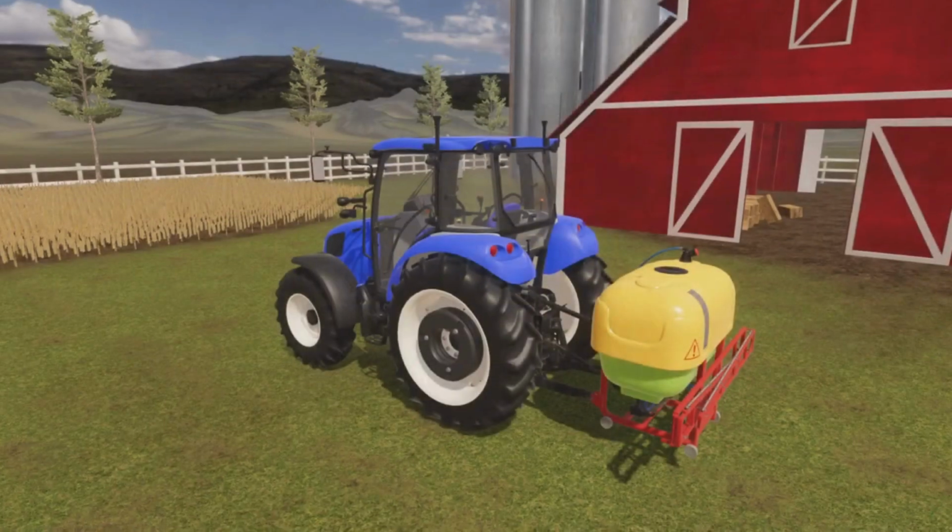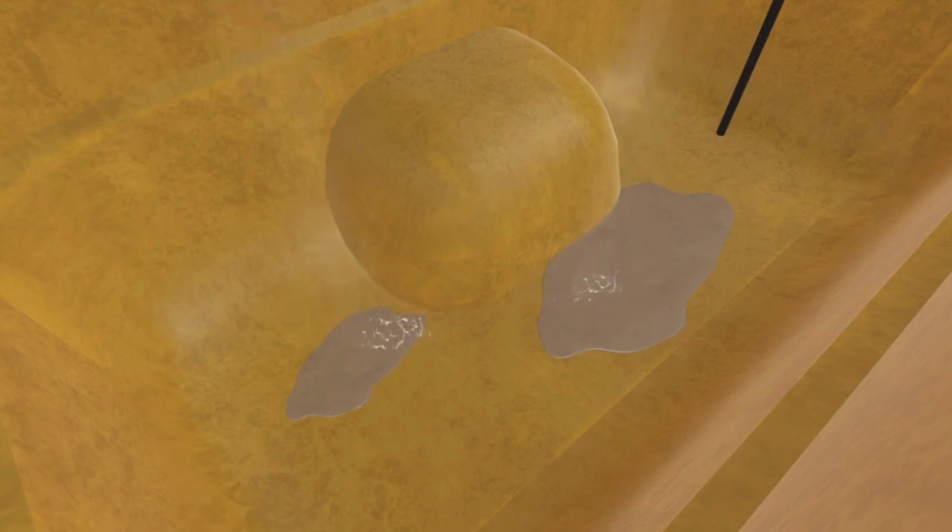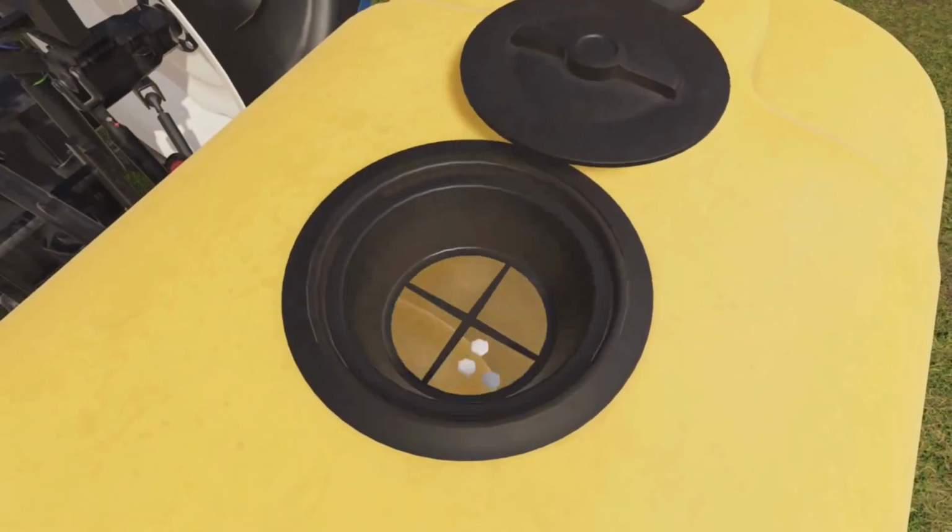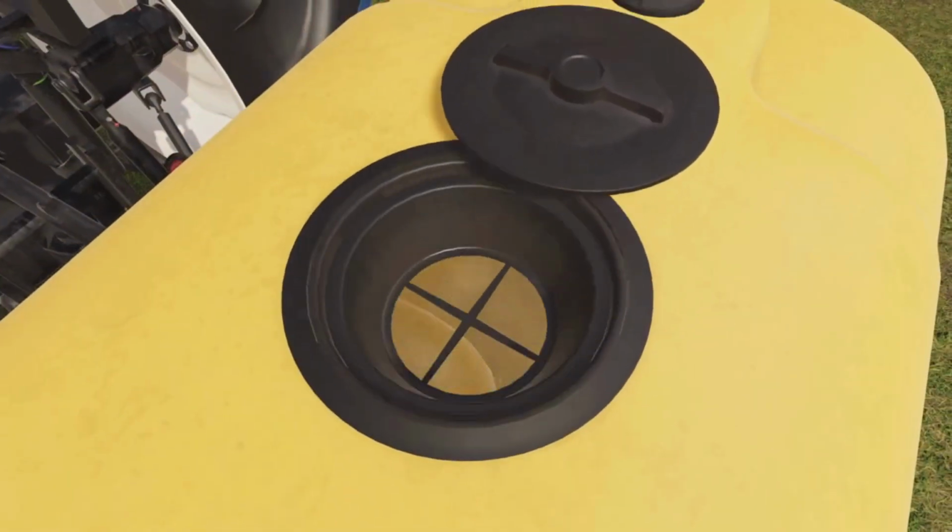Cleaning and checking the tank. Clean the sprayer tank thoroughly to remove any residues from previous uses. Wash it with water and appropriate cleaning agents if necessary. Check the tank, filters, hoses, and nozzle systems for blockages or damage.